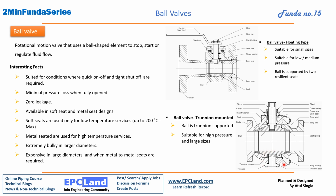If you see here, this is the basic difference. If you compare here, this is floating, this is not resting. The ball is having different type of contact with the seal. Here the ball is resting at one location and it is not changing its contact surface area with the seating arrangement, and it is supported by the trunnion type arrangement. So we are calling it trunnion seal, and it is suitable for high pressure and large sizes.